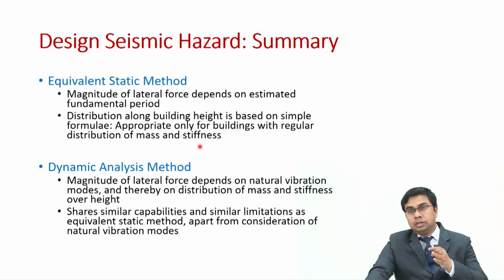However, as we proceed over the next classes, where we will learn about dynamic analysis methods, we will understand that the magnitude of lateral force depends on natural vibration modes and thereby also on the distribution of mass and stiffness over height. We shall look into two different dynamic analysis methods, which are the response spectrum method and the response history method.